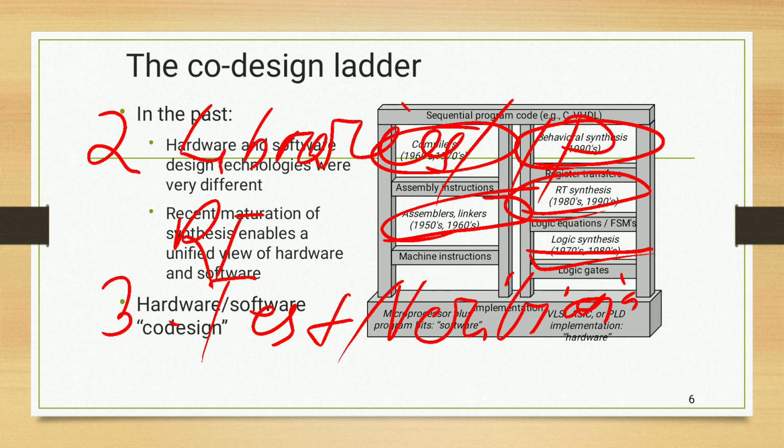First one is the logic level. Gate level simulators provide output signal timing waveform given input signal waveform. General purpose processor simulators perform machine code. And RT level hardware description, that is HDL, simulators carry out RT level description and give output waveform when provided input waveform.